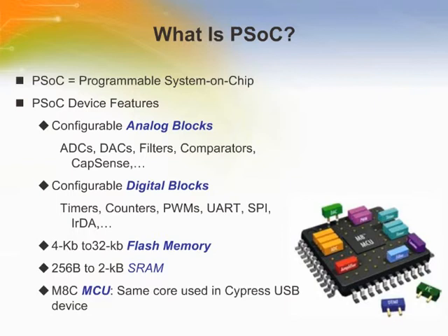The digital blocks can be configured as digital functions such as counters, pulse width modulators, and communication interfaces like UART and SPI. I2C communication is included on PSoCs without the use of the digital resources.